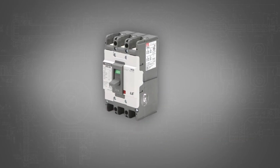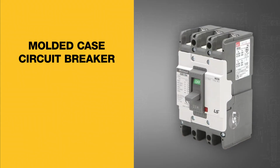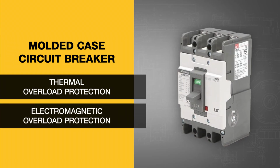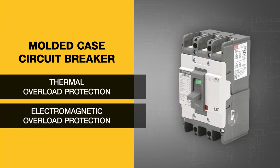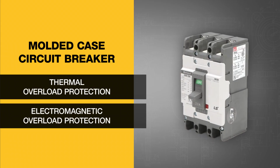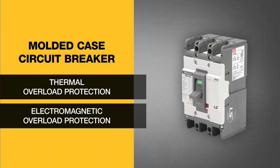The first one I'd like to talk about are the molded case circuit breakers, and these are generally equipped with two methods of overload protection, those being thermal and electromagnetic. The thermal protection consists of contacts that physically deform whenever too much heat is put through the breaker as a result of a high inrush current. These deformed contacts thus break the connection that allows power to flow through.